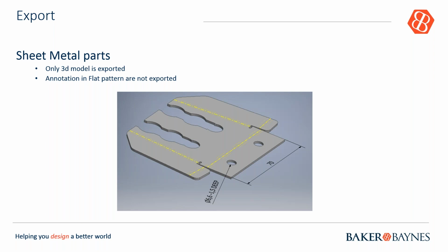If we look at the sheet metal side of it, only the 3D model is exported, okay, and annotation and a flat pattern are not exported. So that's something to take into consideration. When you're exporting out the flat pattern, that does not come in.